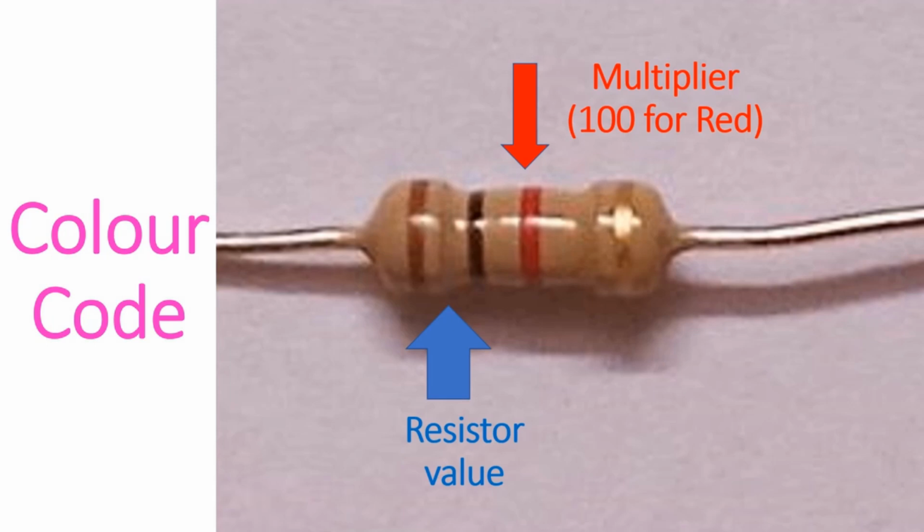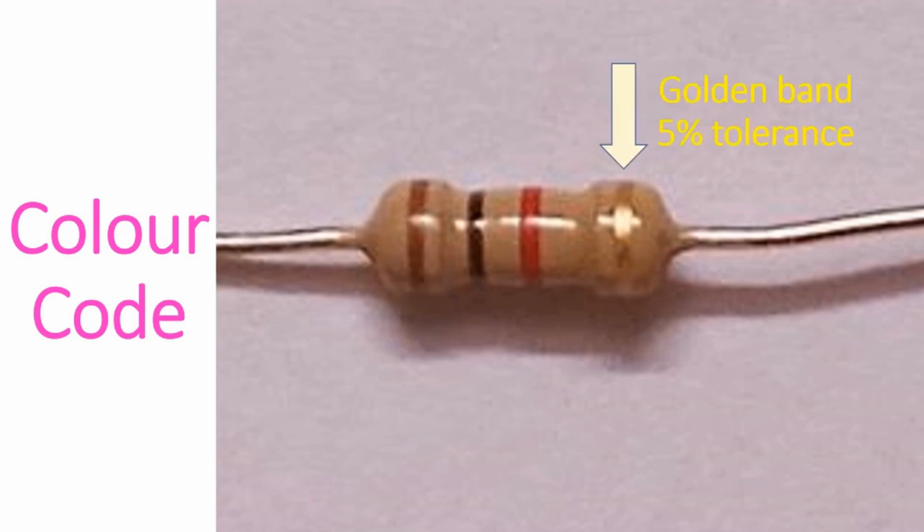First 2 bands indicate the resistance value, which has to be multiplied by the code on the 3rd band. 4th band indicates the tolerance. All the resistors shown here have a golden band for the tolerance, indicating 5% variation above or below the coded value. If there is no tolerance band, the tolerance is presumed to be 20%.